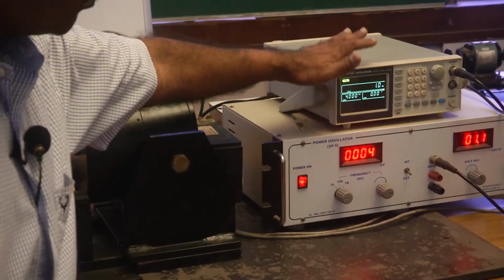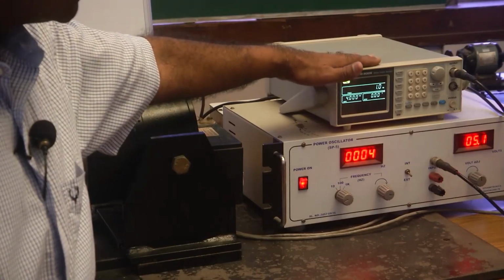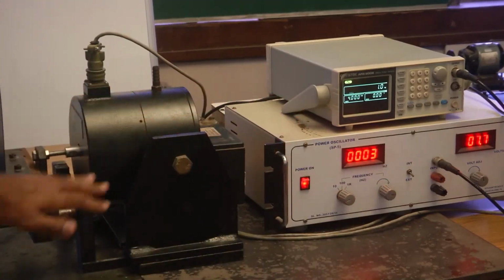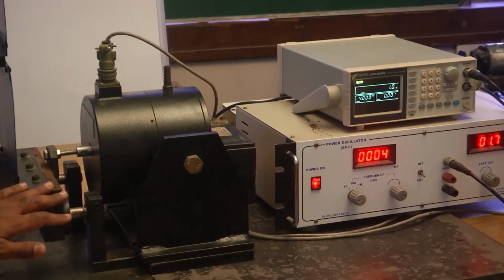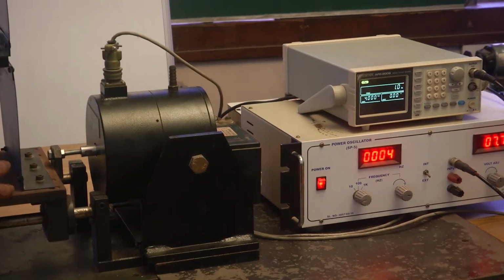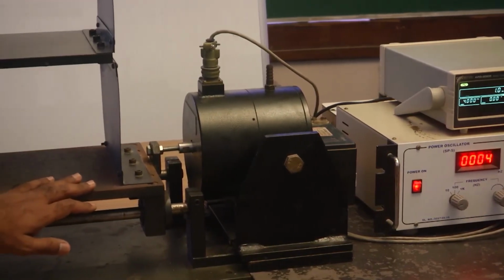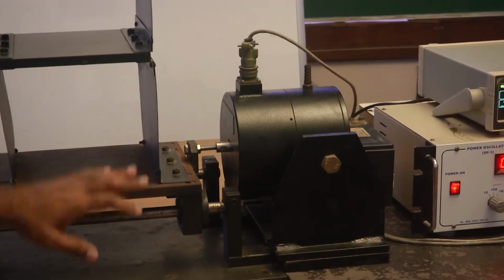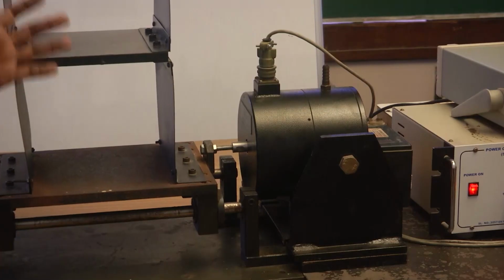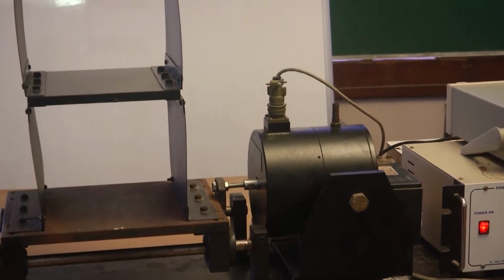We have initiated a harmonic signal of a given frequency using this signal generator, fed it through the power amplifier to the oscillator, so that the base motion to the base plate here can be adjusted based on our requirement. So, if this base or the whole vibratory system is excited at its base with a frequency that matches with one of the natural frequencies, the corresponding resonance phenomena is going to be evident, and at that particular resonance phenomena, the displacement pattern is going to conform to the given mode shape.